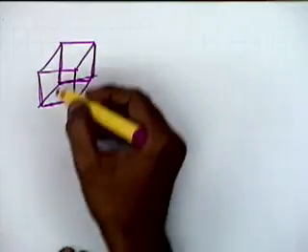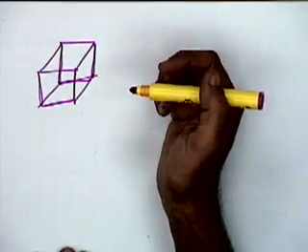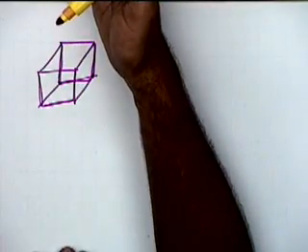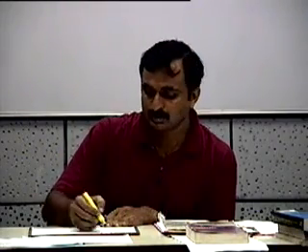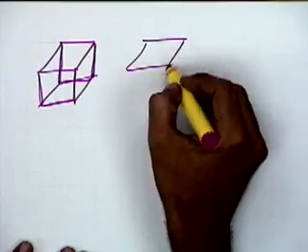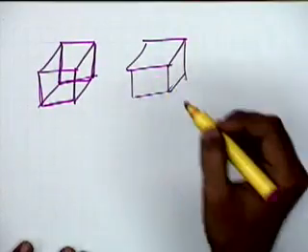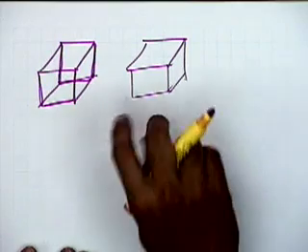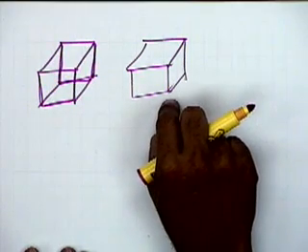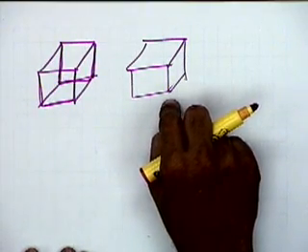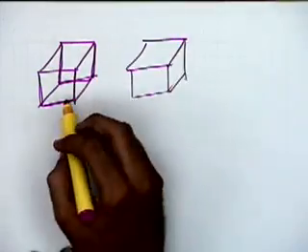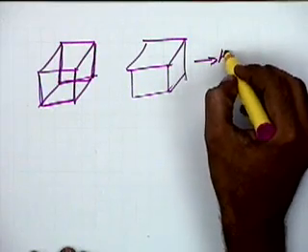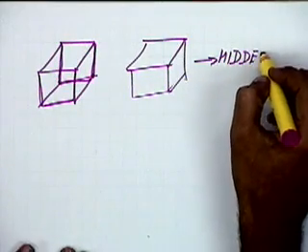So normally we like to remove the hidden surfaces, the surfaces at the back which are not visible, the edges which are not visible. We like to remove those lines and edges. So instead of drawing it like this, we like to draw it just like this. This would improve the clarity of the presentation. It will help in visualization. So when we are talking of display, we like to remove hidden lines. This is normally referred to as hidden line removal or hidden surface removal.